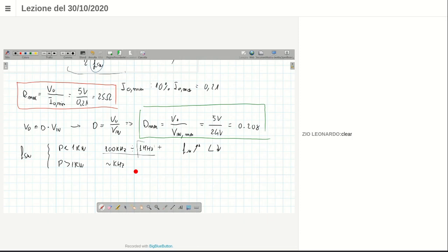Typically, while the frequency is increased, switching losses become more and more relevant, whereas while reducing the inductor and the ripple, conduction losses can possibly be reduced. So there is a trade-off. If you increase the switching frequency, you may have more problems in terms of interference.